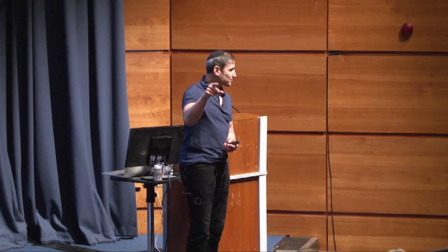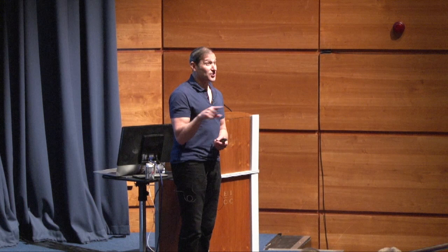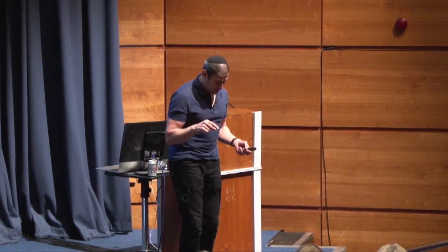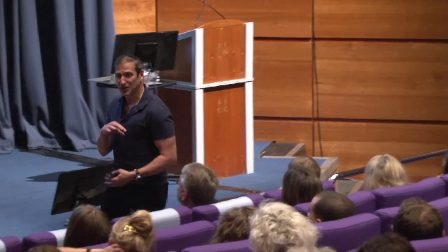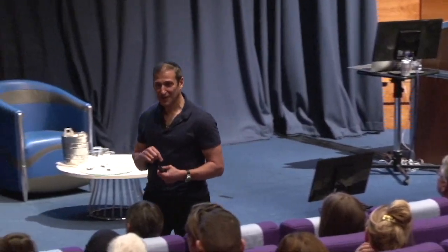I'm going that way. And so if there's a wire or a lead, you can pretty much rest assured you're going to be inducing currents inside that wire or lead in magnetic resonance. And if that wire or lead is even partially within the region that is undergoing direct radio frequency irradiation, be really careful where the other side of that is.